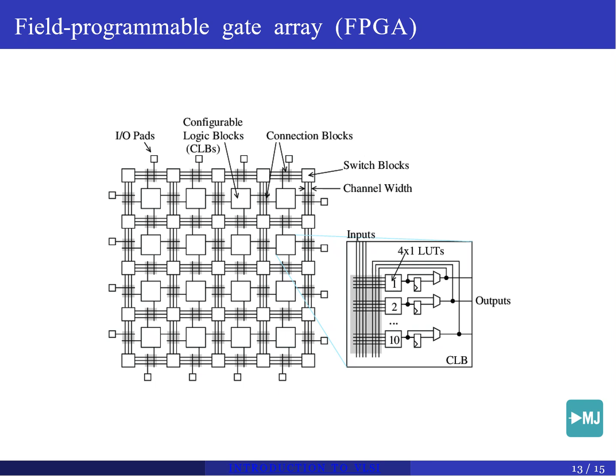and flexibility. Next, when you come to FPGA, think of an FPGA as a chip that is a blank slate of logic blocks and wires that are already manufactured. Your job as a designer is purely to program the connections between these blocks to create your digital circuit. This is the fastest method to get a working prototype, and it is incredibly flexible because you can reprogram it over and over again. This is like buying a prefabricated home where you can instantly rearrange the walls and wires with the push of a button.